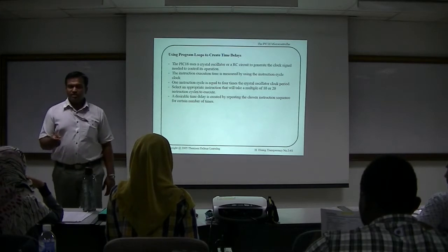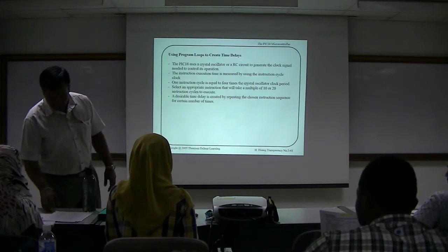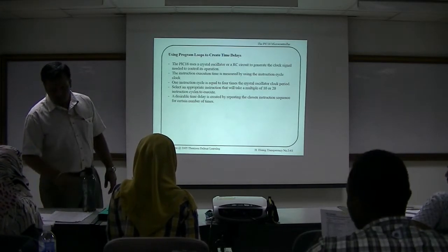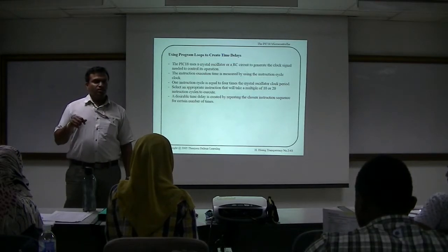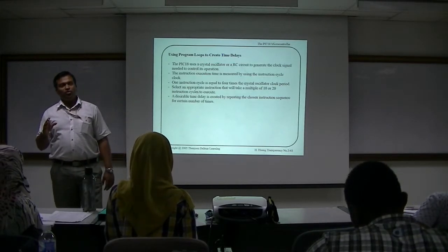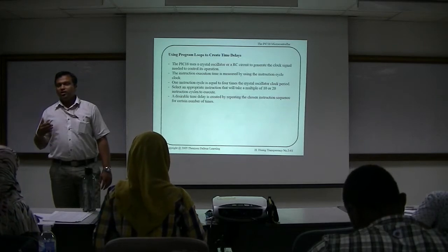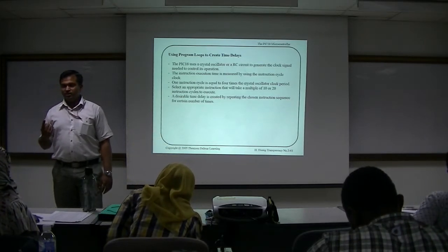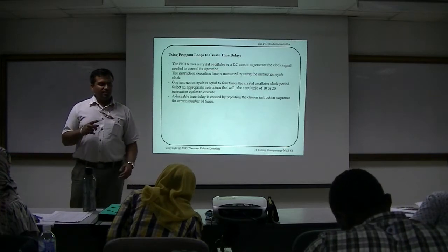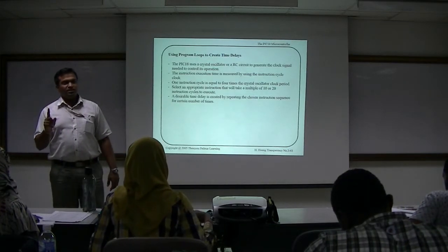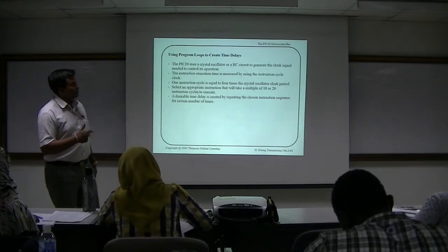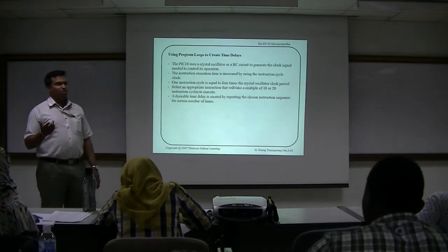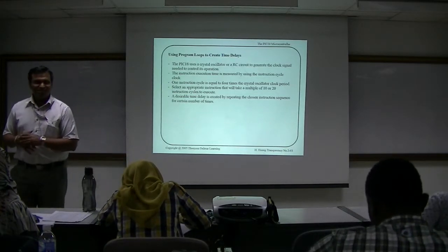For example, if you see the first instruction, ADDWF, cycles is mentioned as 1. So that means in order for the microcontroller to execute that ADDWF instruction, it takes 1 clock cycle. Do you understand the term? That's what it means. One means it takes one instruction cycle clock. Good terms.